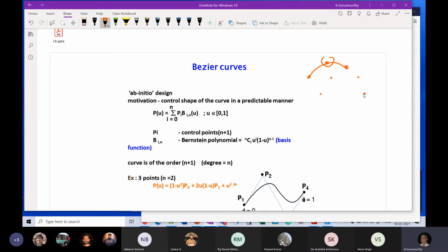The question I ask you is, what kind of a shape does this imply to you in your mind? Clearly, these 4 points do not imply a shape like that, nor does it imply a shape like this. The more logical thing would be a shape like that, right? That's the intuition behind this whole Bezier curve, that the user, in some sense, nudges the computer to the shape that he or she is interested in by picking these points. Likewise, if the user pulls this point upwards there, one would expect that the shape that he or she is interested in looks like that, right?